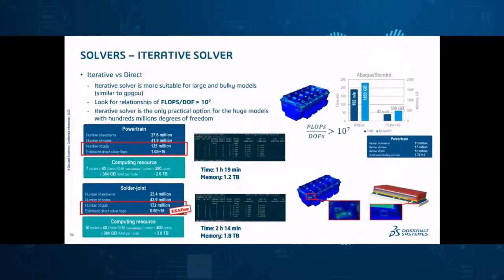So to cover off a couple of options that are available for certain scenarios, which again could help improve performance. Firstly, if we look at the iterative solver, there's some things to consider to determine if the job that you're running is a good candidate for the iterative solver. So jobs that tend to show the greater benefit are ones that are more densely packed and bulky models, such as powertrains, and less so for sparse shell-dominated models.